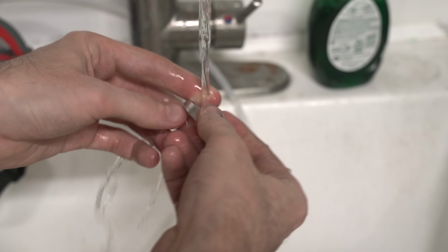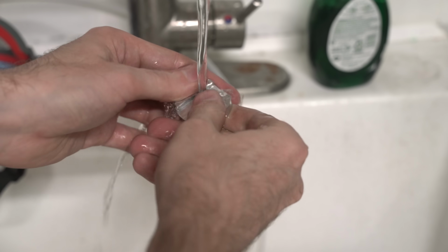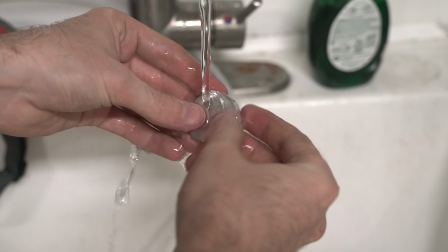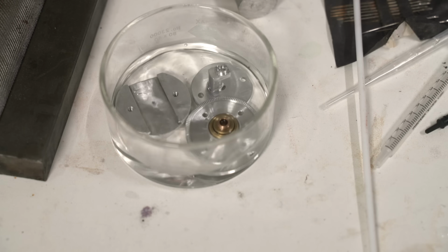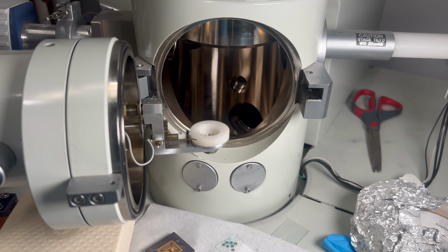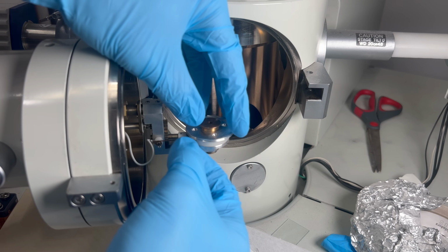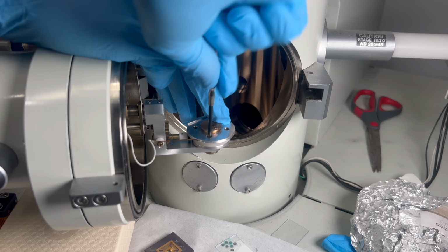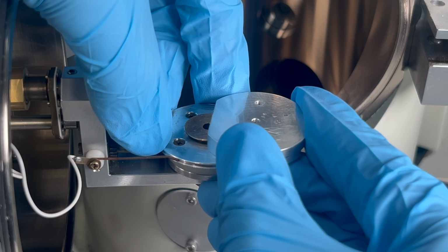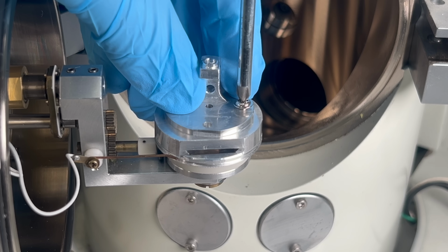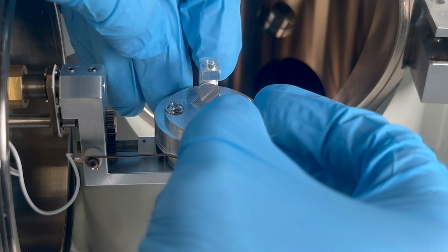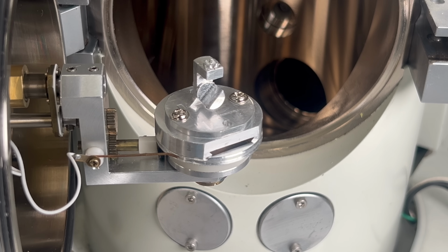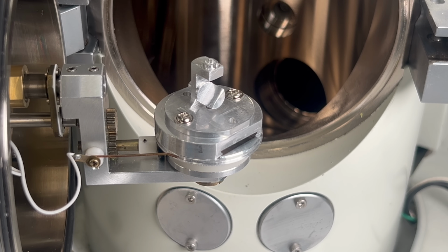Awesome. Before we put anything in the SEM, we need to clean the parts to remove any oils or metal dust. I wash them with soap and water first, then give them a quick bath in acetone. Finally, it's time to test the STEM-in-SEM adapter for real. I first reinstall the mounting bracket that I removed earlier. Then I slide on the aluminum base plate and screw the sample holder onto that. Next comes the movable mirror. For the first test, I want to see what it looks like empty, without a TEM grid or shield installed.